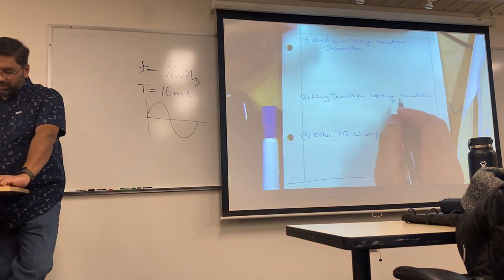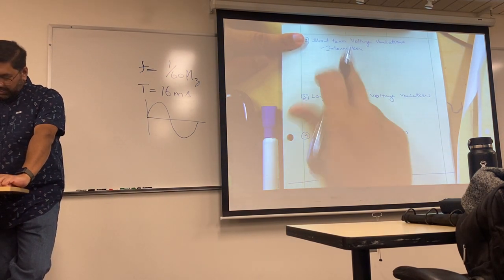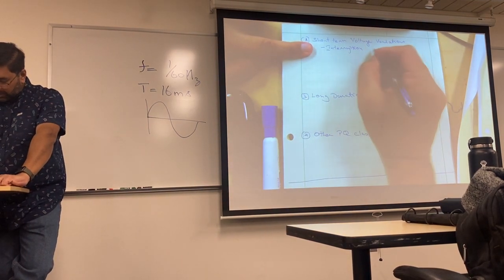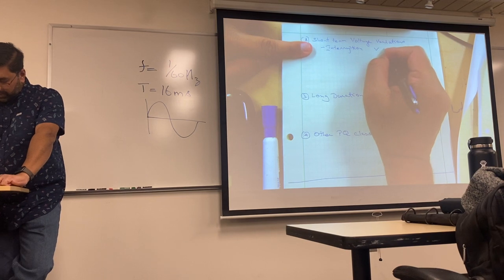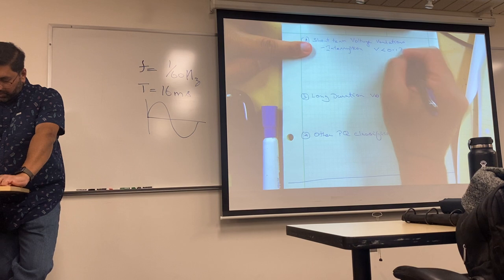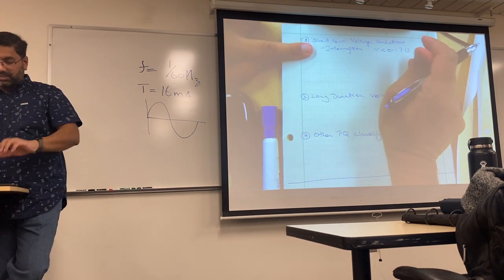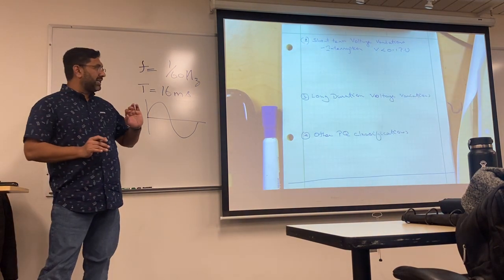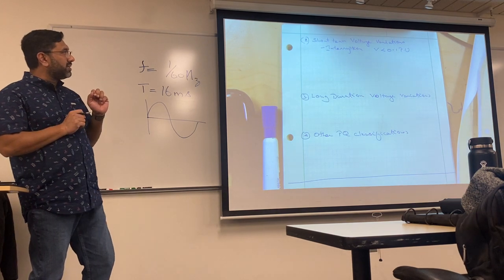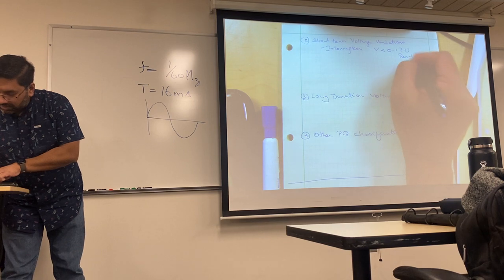So both short and long term have interruptions. The thing here is with short term interruption, I'm talking about a voltage loss of like 0.1 per unit. And I have to tell you what a per unit is. We have an entire lecture dedicated to this, but I'll explain it in a broad 30,000 foot view of what a per unit is. So PU, because you're seeing it for the first time, let's just write it as per unit.